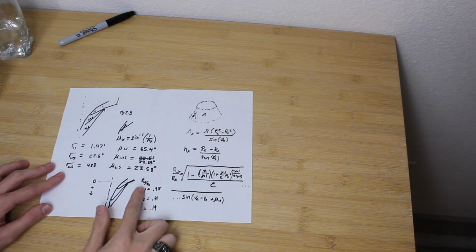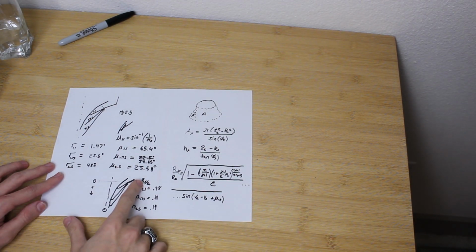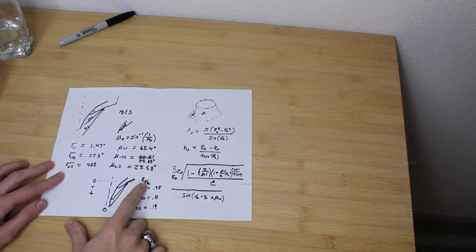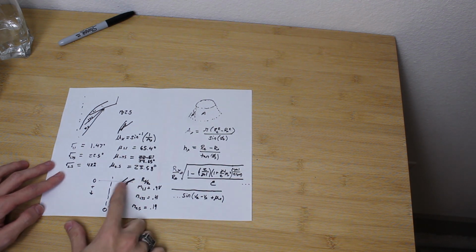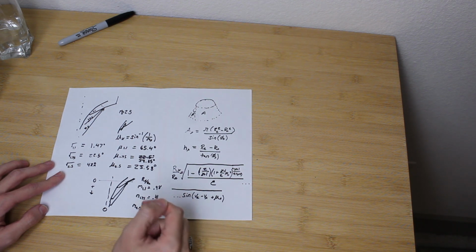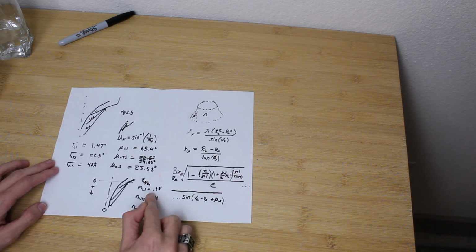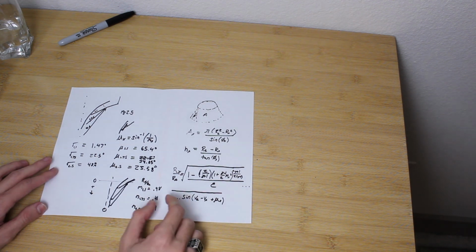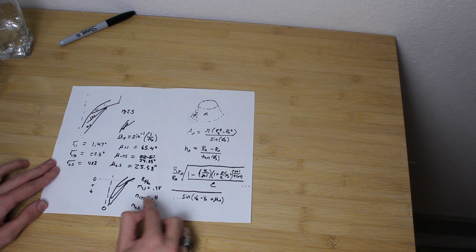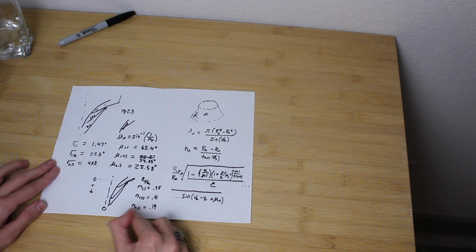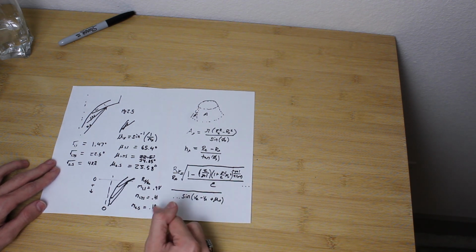Alright, so I've gone ahead and computed the radius as it pertains to the initial radius for the following parameters. For Mach equals 1.1, the spike is 98% of its full diameter. For 1.75, it's 41% of its full diameter, and for Mach 2.5, it's about 19% of its full diameter.